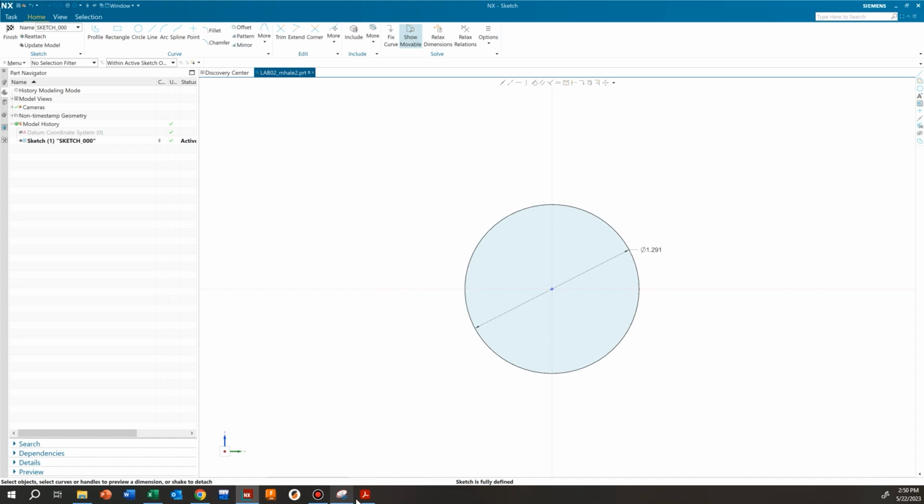And we're going to sort of draw that chamfer. So I'm going to come up here to profile, and I'm just going to kind of draw it. Ideally we'd be on this line, but I'm going to go past this line just a little bit across that horizontal line, and hit escape to cancel out of that line. Then I'm going to draw a line that splits this circle in half. I'm going to start from over here and go all the way through, and hit cancel again to exit out of that.